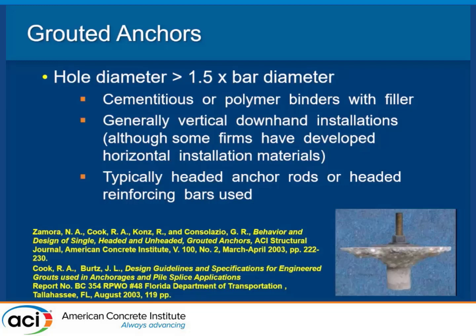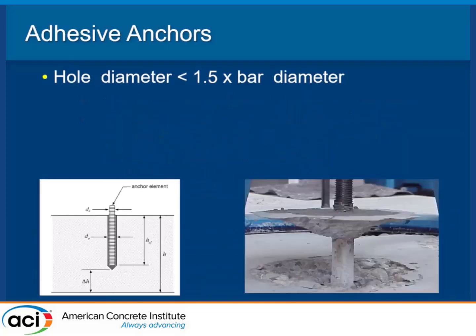You will find some directions out there on how to use a grouted anchor, if that is something you're really interested in. Adhesive anchors we do cover, and they have a little bit tighter hole, largely to save a little bit on the epoxy. The biggest problem we generally have with adhesive anchors is a bond failure. And once again, the biggest reason for bond failures is the hole. We didn't clean out the hole properly. We didn't do what the manufacturer told us to do.